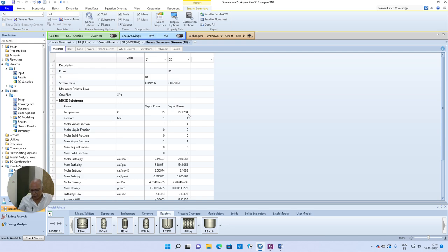In fact, this is normally one of the cases which can be used. The excess reactant is going to regulate the temperature increase. But remember, if you have highly exothermic reactions, normally we'll be either adding one of the reactants in excess or adding some kind of an inert to increase the mass so that the temperature increase is under control. But what is the penalty that you may be looking at?